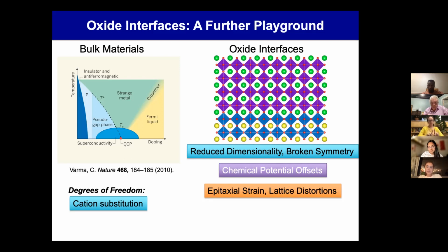So we can think about a material that has a lattice constant where the atoms are spaced maybe 3.9 angstroms, and then we put a material on top where it wants to be 3.8, but it's going to stretch to follow that underlying template that we deposited on. And we could think about changing lattice constants by 5 or maybe even 10%. And so this is actually quite profound.